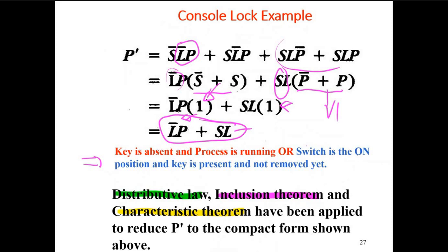I'm making 1,000, 10,000, 15,000, who knows, per year. Would I lock up a PLC, which by itself in this case would cost you 250 plus? Not going to make any money, or the other person is not going to make money, or you're going to pay a lot more money. One of them. So if it is a fixed automation, I can go through another route. What is the another route? Okay. So you know the AND, the OR, the NOT operations. They are available as chips. You can buy them in bulk for 10 cents, 20 cents.